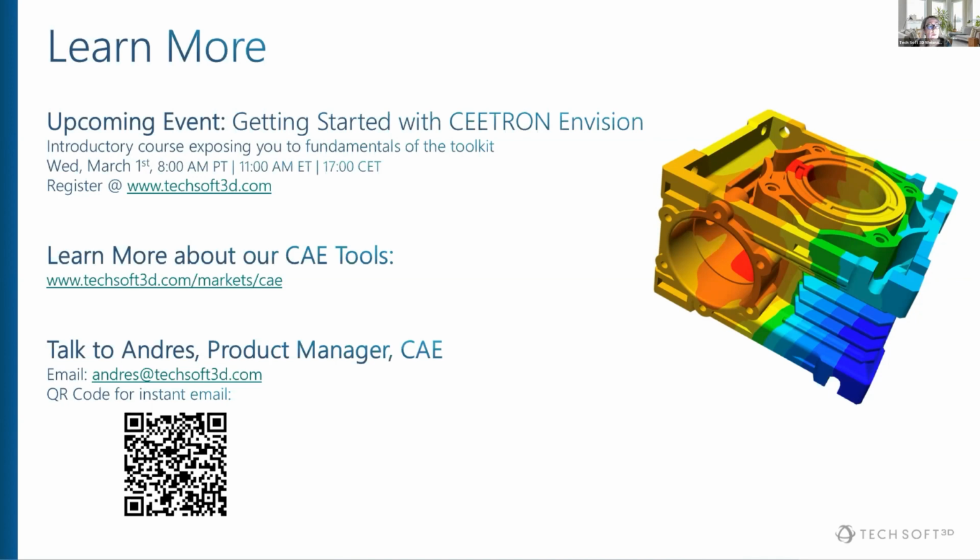Perfect. So I'm looking through here. Does CEETRON Mesh support beams, one-to-many, and many-to-many mesh? Also, does it support contact definition? Well, could you repeat, please? No, CEETRON Mesh is really about mesh generation. I don't think we have 1D elements there. It's really about 2D and 3D meshes. And contact would be handled by the boundary conditions and the solver itself. You'd have to define sets and stuff like that. But it's not in the mesher. The mesher is about really generating the mesh. Great.